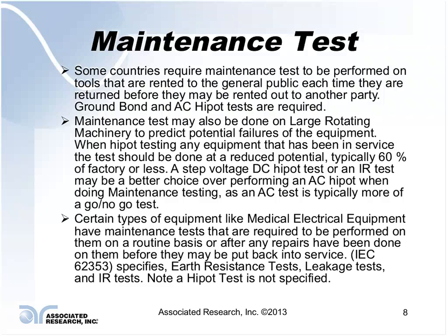Why? Well, over time, insulation will age. It could possibly be damaged. It could crack. The insulation itself could dry out, become brittle. Moisture could be absorbed into it. So the insulation itself could be degraded over time. Now, you kind of have to ask yourself the question, isn't this something that I want to detect in doing this test? That's the whole purpose of the Hipot test.